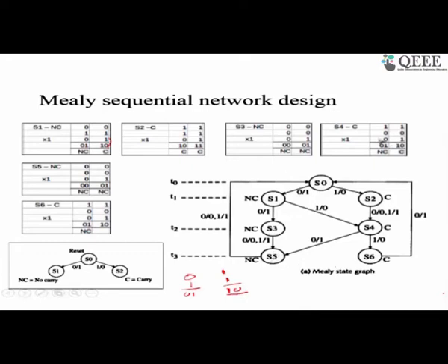Okay. So here on S4, because there is a carry we have to put a 1 1. No bits need to be added for conversion sake, but the bit can be a 0 or 1. Accordingly we get either a no carry or a carry state. So on a 0, what do we do in S4? On a 0 we output a 1 and go to a carry state. That is what this transition represents. On a 1 we output a 0 and go to a carry state.